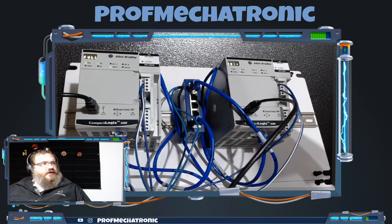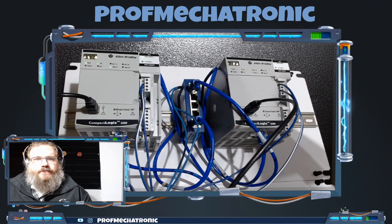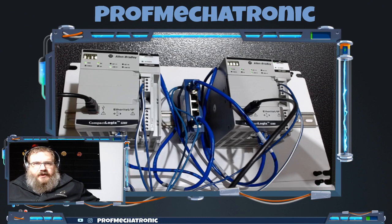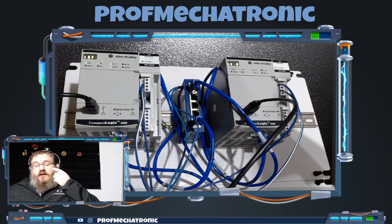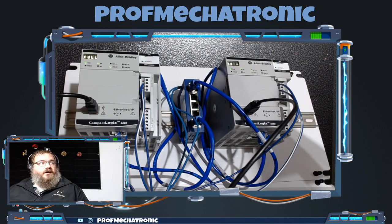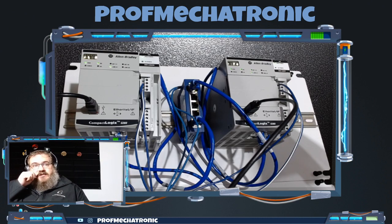Now, what you'll find here is that we also have a network switch in the middle between them. That's just a standard unmanaged 5 port network switch. It takes 24 volts DC to run. Typically, we need one of those anytime we're connecting communications protocols together, because Ethernet communications requires the transmit and receive wires to be flipped.